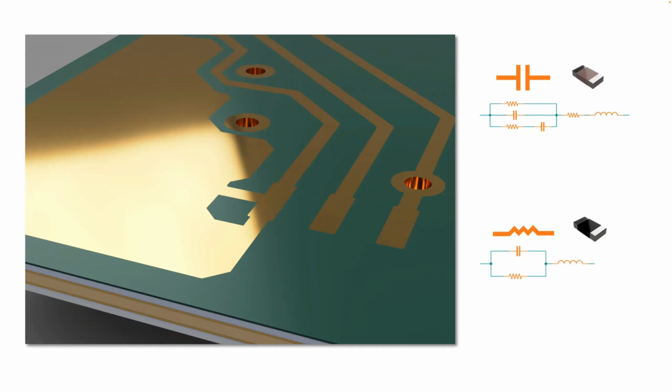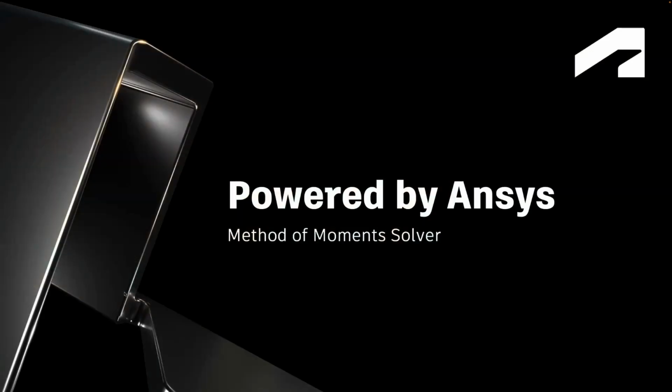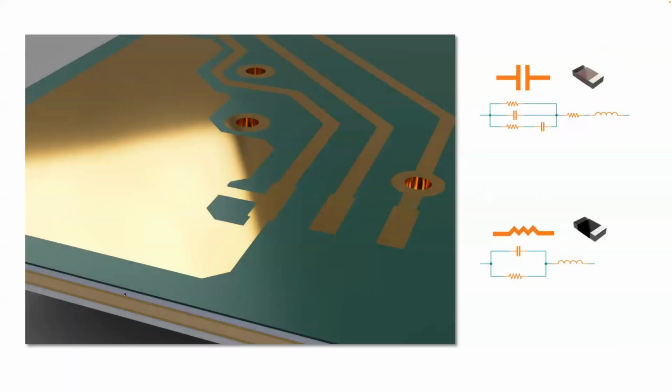That capacitance is one of the defining elements, oftentimes more crucial than things like inductance, in calculating an accurate impedance. And I saw some of the poll questions earlier related to how you calculate these things. Online calculators are good as a general concept to point you in the right direction for a highly idealized version of the board, but they are, for all intents and purposes, the SPICE equivalent. They're idealized. And so much of what we are trying to drive on the signal integrity side is how do you get your eyes into the PCB?